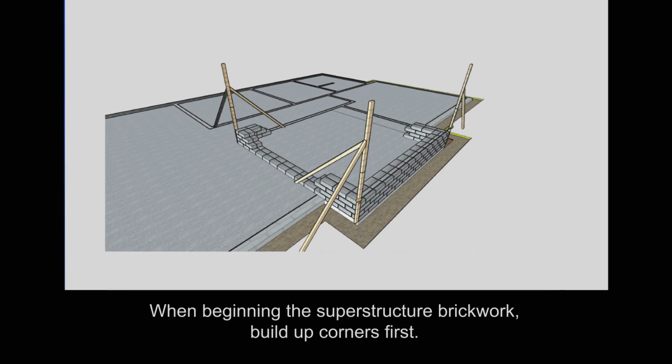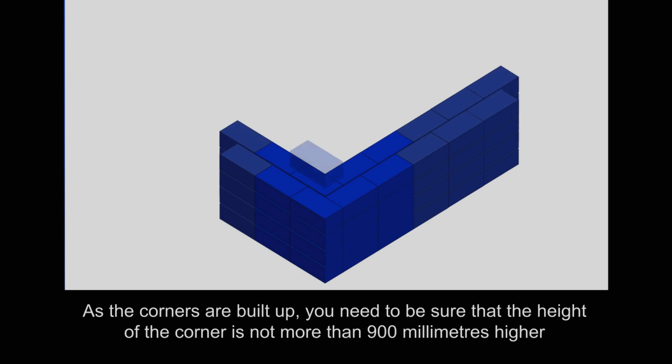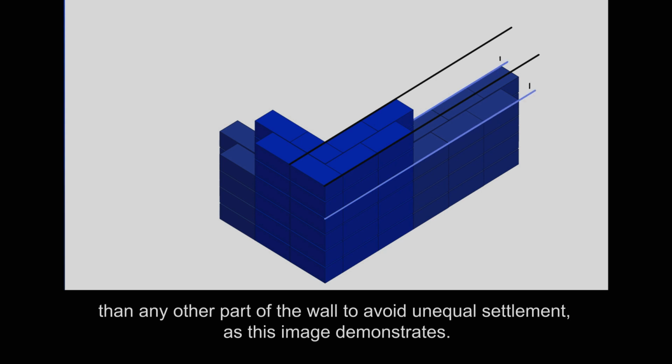When beginning the superstructure brickwork, build up corners first. As the corners are built up, you need to be sure that the height of the corner is not more than 900 mm higher than any part of the wall to avoid unequal settlement, as this image demonstrates.